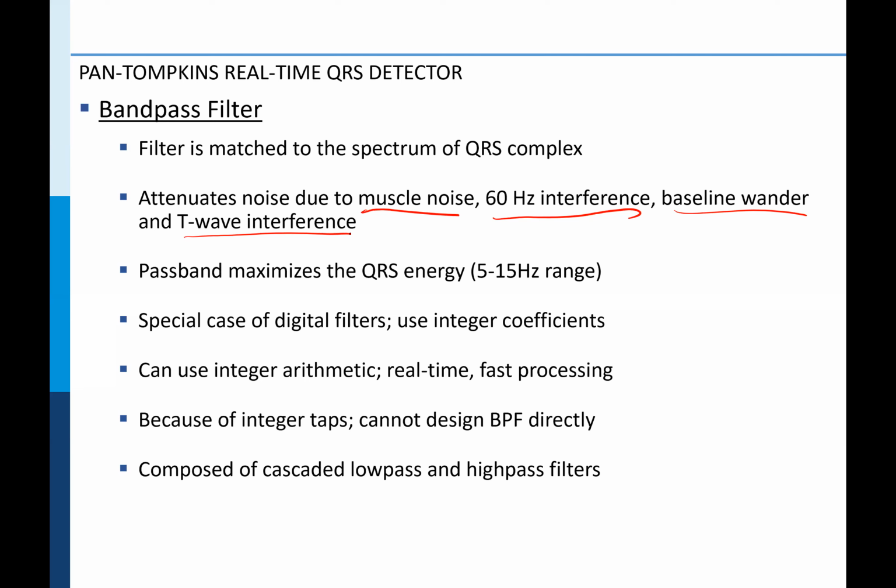Okay? And it also ensures that we are maximizing the performance of the filter in the range of 5 to 15 hertz, which really enhances the QRS complex. Okay? So the frequency of interest in this block diagram is between 5 to 15 hertz.